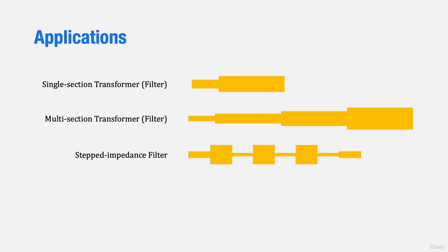Engineers have taken advantage of transmission lines and cleverly used them to design filters and other functional components, even replacing inductors or capacitors. For instance, we can deliberately use impedance discontinuities and control the line length to reflect signals at certain frequencies and prevent them from reaching the load.